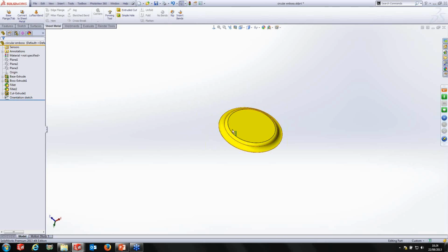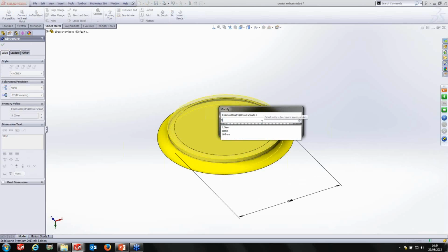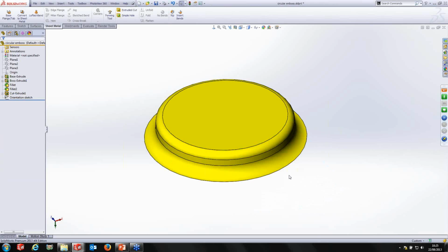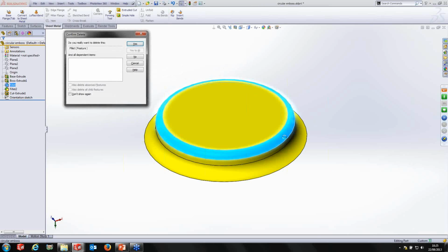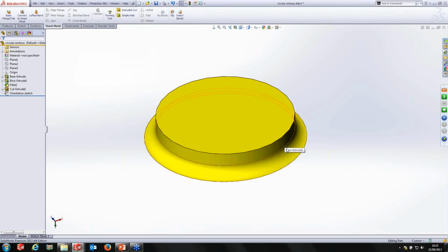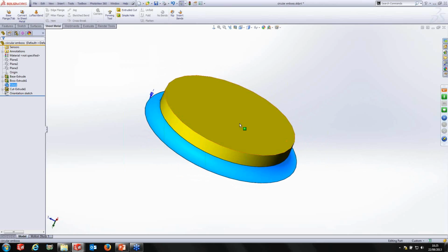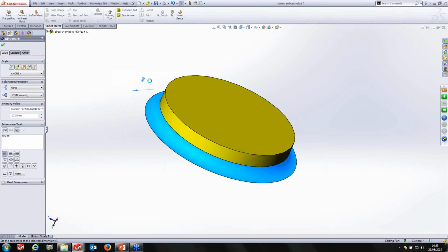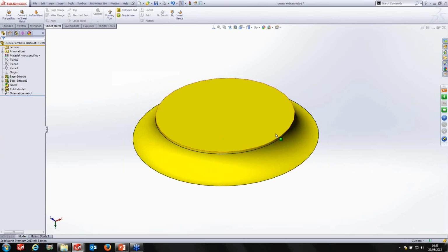Okay, now if I want to modify the shape of this item, I can just double click and I can adjust some of the dimensions. So I'll put this one to 11 millimeters. I'll size this up to 60. Okay, and I'll just hit Control and Q to rebuild. And then I want to remove this fillet. I'm also going to size this one up. We need to make sure that any of the fillets we're inserting are larger than the thickness of our material. So that radius of 5 millimeters, I'm going to size it up so it's larger at 10 millimeters in radius.